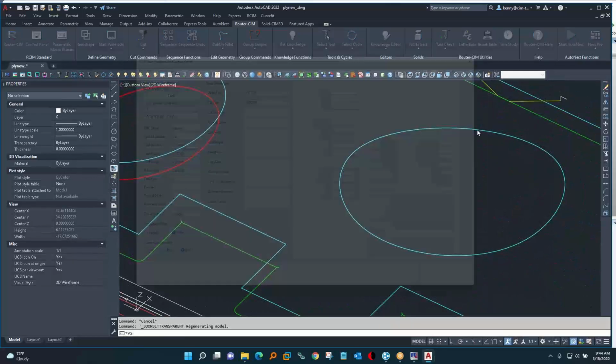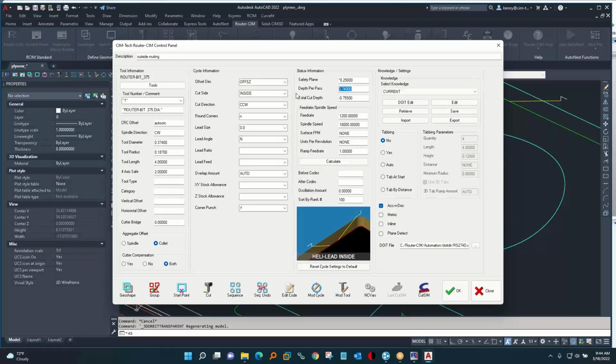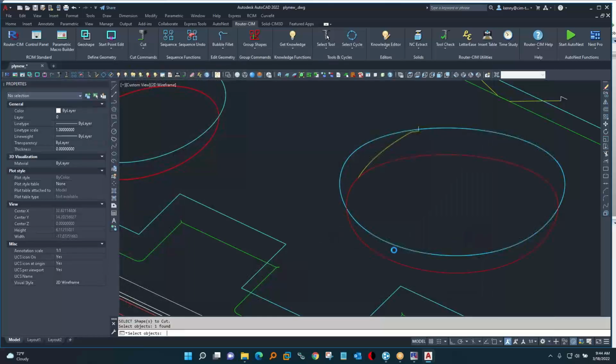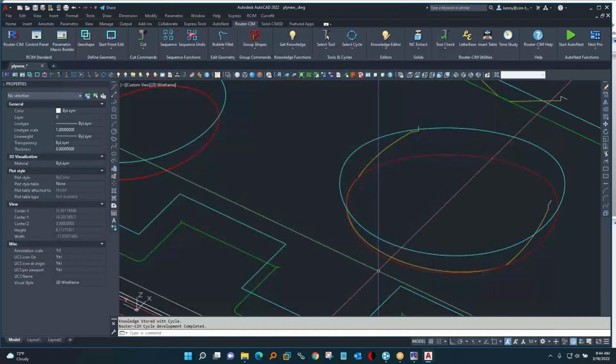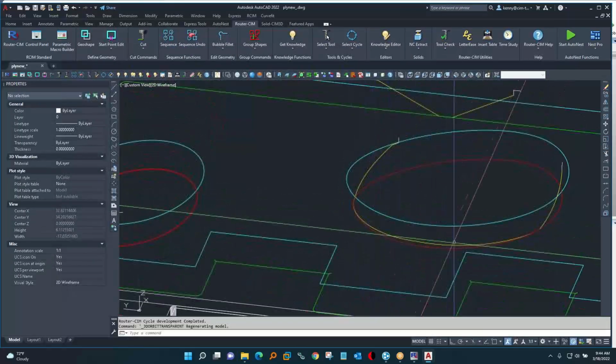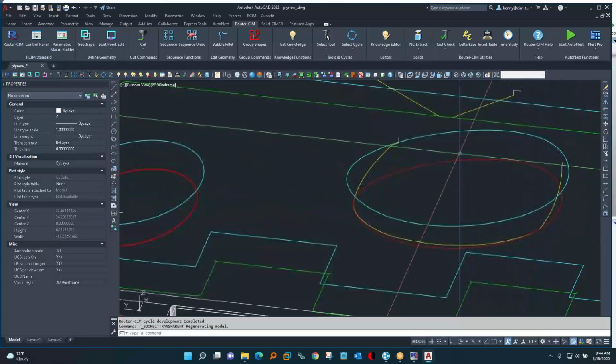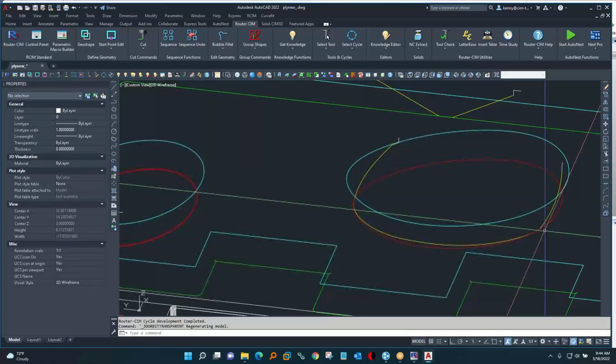So instead of twice around the part, we can do something where we go, for example, 1.5 times around the part. We do what's called a tab at cut start, and I could put in a decimal percentage there. And when this makes a cut, this leads in and right away makes a tab, cuts around the shape, then the overlap cuts the tab off.